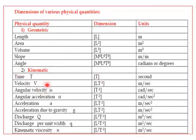So velocity is length by time, so LT^-1. Angular velocity is again radians per second, so therefore it is 1 by T, that is T^-1. Similarly, angular acceleration is radian per second square, so therefore it is T^-2. Acceleration is meter per second square, so therefore LT^-2. Acceleration due to gravity again is meter per second square, so it is LT^-2. And discharge, you know that it is volume by time, so volume is L cube and T^-1.